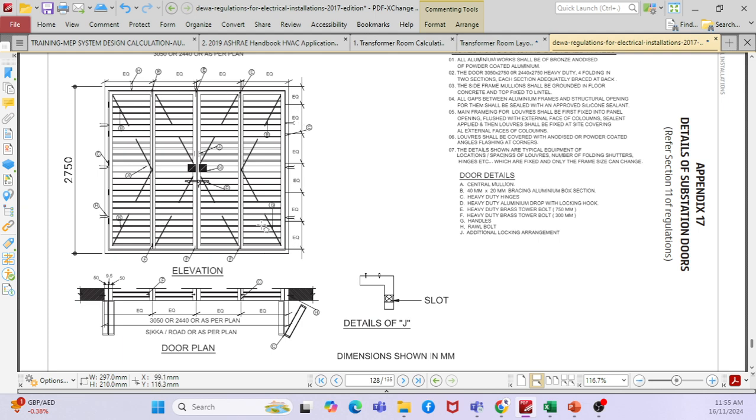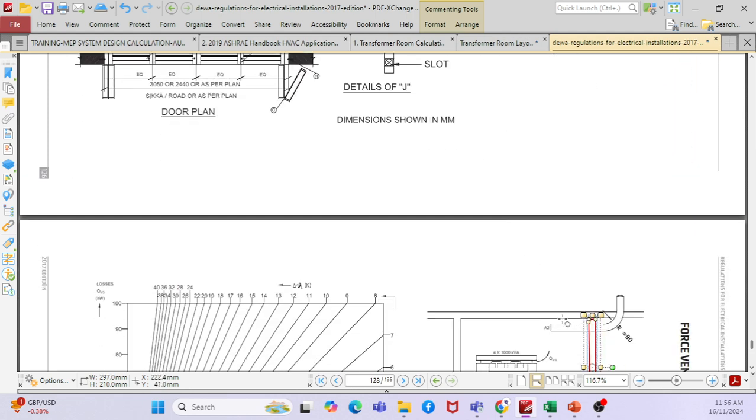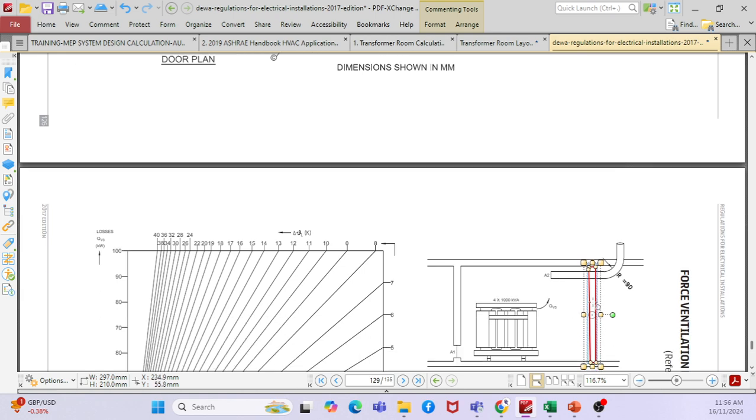So we have to make sure that this particular pressure drop is considered in the fan. Whenever you have a fan here, that pressure drop is considered. Okay, say for example, if I have 50 pascal, then I have a ducting, whatever the pressure drop is should be calculated, then you have to consider it in the fan calculation.